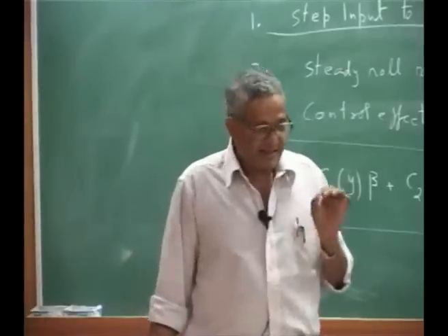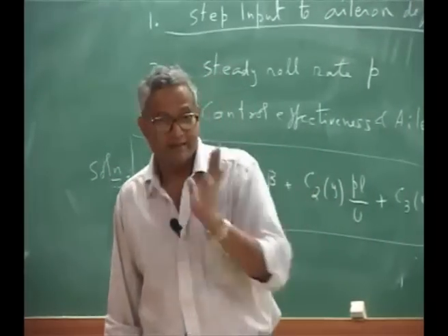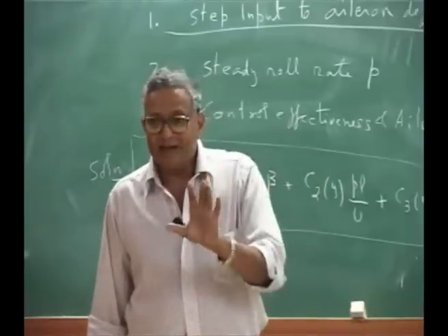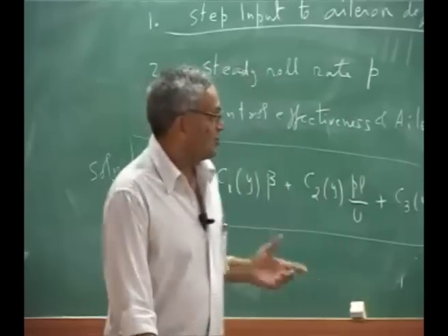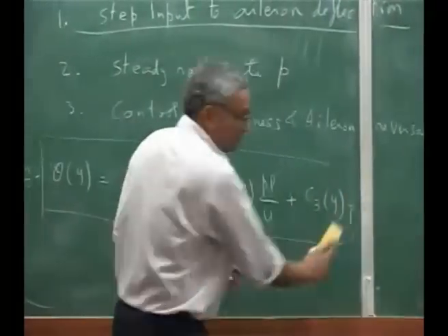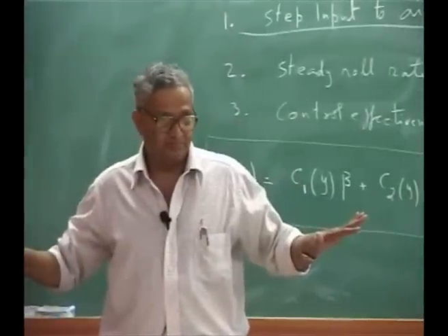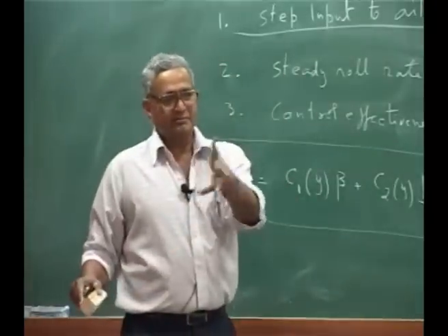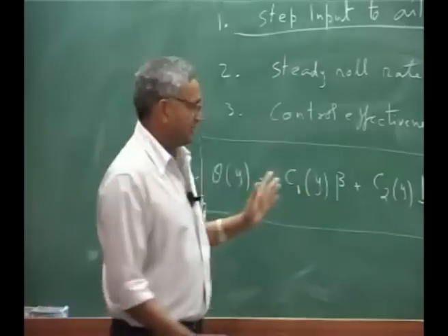That is why, according to Newton's law, F is ma. Similarly, moment is I alpha. So I will have a roll acceleration. So what you have to solve is, first problem, my roll velocity at that instant is 0 when I am starting. Then you can integrate how the roll acceleration changes with time, then you can get the velocity, etc. Okay?